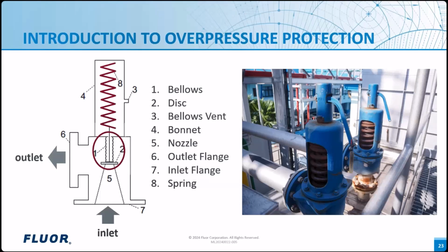The orifice is sized based on the estimated required flow to relieve the overpressure. The fluid characteristics, such as phase (liquid, vapor, or two-phase), density, temperature, etc., are used to determine the minimum required orifice area. In addition, special care is given to both the inlet and outlet piping sizing to ensure adequate performance.